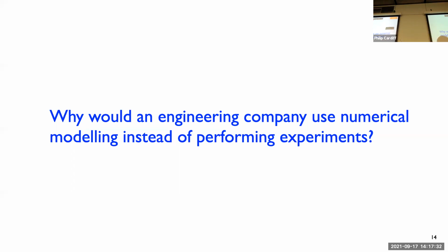So if you do a test, say like in the metal forming examples I gave, or actually any of the examples, like the wind pedestrian case, there's certain things you just can't measure experimentally. So if you want to know what's inside that metal forming product, like the distribution of permanent plastic strain, and you want to know the distribution of stress and strain or other things like where the rollers might break, that information is almost impossible to get in an experiment situation. And so when you have a model, you can just look at the value of anything anywhere, and that's just not possible in an experiment. So there's insight that you gain from models that isn't as easily or as readily available from other methods. It might not give you an answer yes or no, but it might help along with experiments for you to solve whatever problem you're interested in.